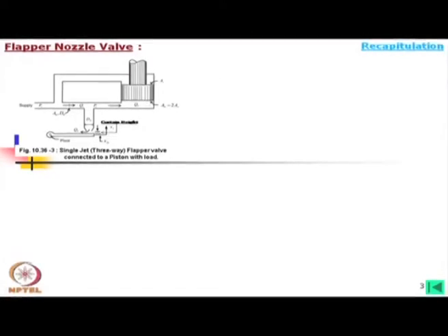this piston head side, but that is again controlled through an orifice, and part of the oil is allowed to go back to the tank through an orifice, the opening of which is controlled by a cantilever beam, that is basically a very thin plate mounted, pivoted on a pin, this pivot, and then this is moved by some mechanism.